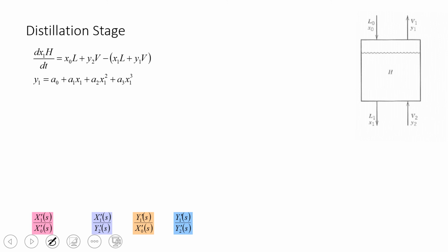Okay, so let's go on then. Let's go ahead and work through this. I encourage you to try this on your own, but you can use this video if you're getting stuck with this problem. The first thing we need to do is linearize and put into deviation variable form, so we can transfer into the Laplace domain with 0 initial conditions, and there'll be linear terms as well. Okay, so let me go ahead and linearize the right hand side of this.